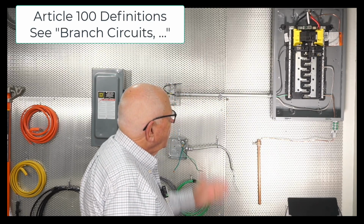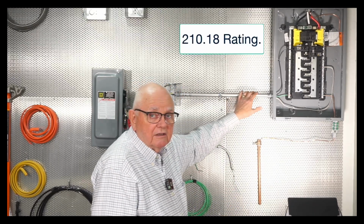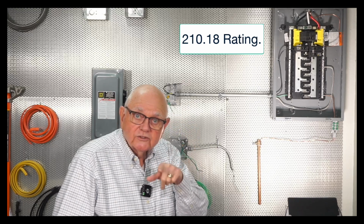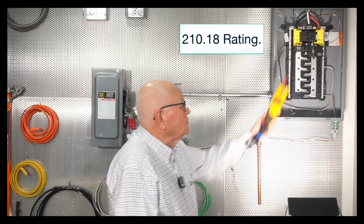Now, some things. First of all, the size of the branch circuit. This is number 12 THHN. So we know it will carry more than 20 amps. We can look that up in 310.16, can't we? However, Article 210 tells me that, hey, the size of this branch circuit is whatever size that overcurrent protective device is. So, some terminology then.